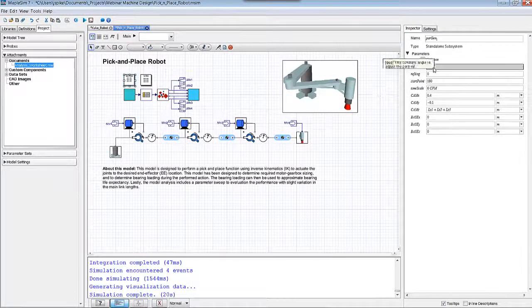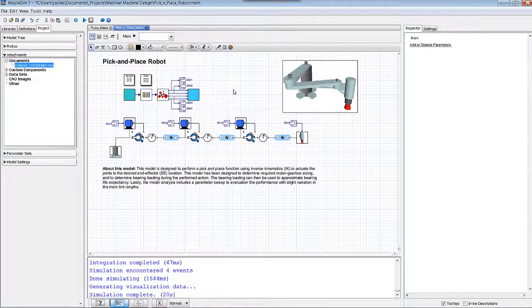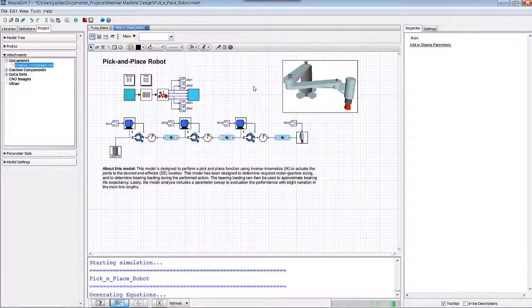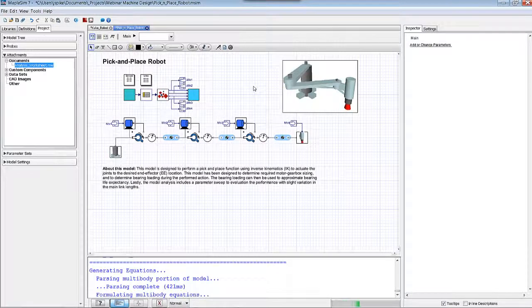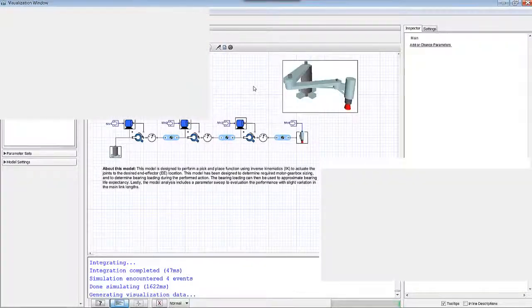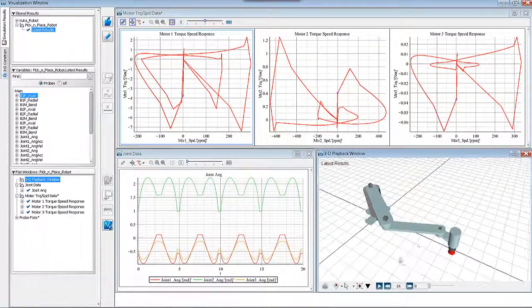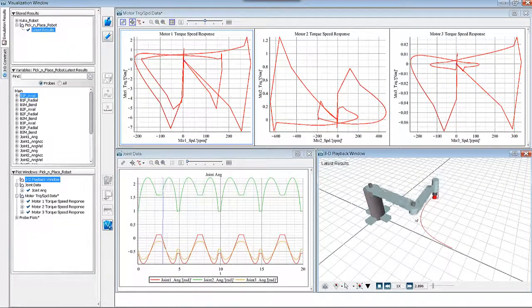We have the ability to always go back, change any of the parameters we may have, such as our gear ratios. I can change my gear ratio 1, gear ratio 2, and gear ratio 3 to a completely different configuration and simply run those results again. The model is allowing me to have a very parametric approach to this analysis without being confined to limitations that may occur by selecting a motor and configuring it with a DC motor that we saw in the first example. This allows me to examine different possibilities, such as what-if scenarios, and consider that my design may change and I may need to go and have multiple iterations in my overall workflow without being tied down into any decision making that I may have further in the process.